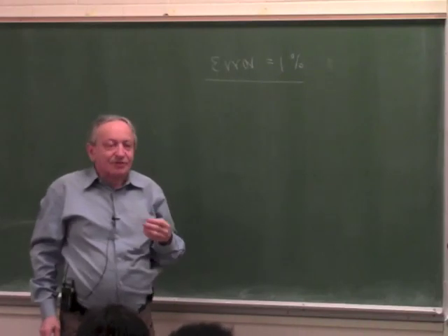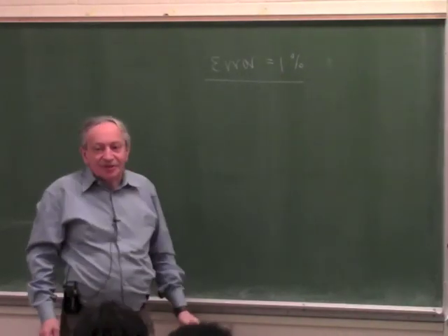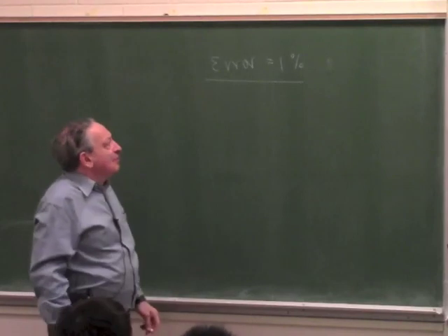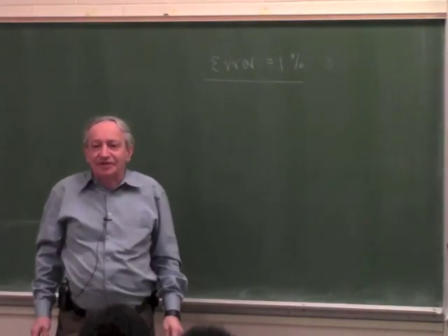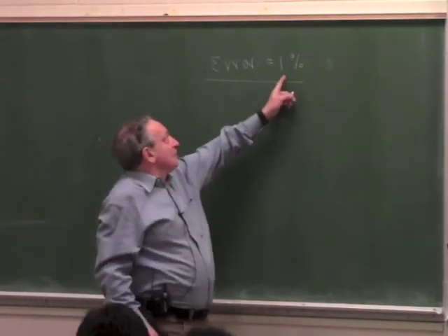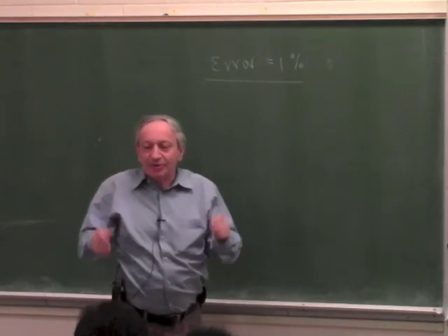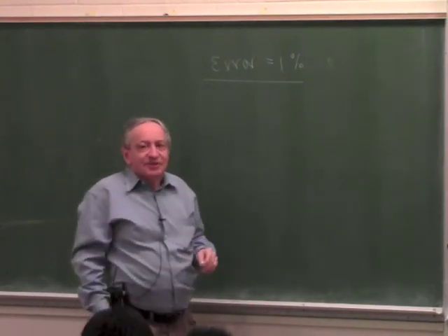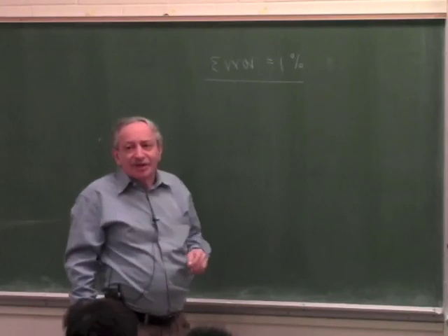Okay? So that's also a common error of inexperienced designers, because they say 1% is 1 part in 100. So that's total error, not plus minus. Total error band 1%. So inexperienced designers say, okay, 1% is 1 part in 100.